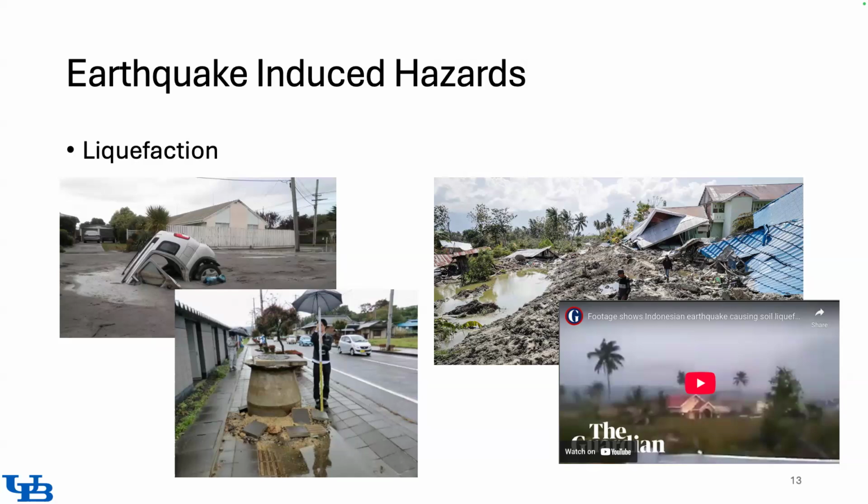And since the pore pressure is increasing, the effective stress is less. That essentially makes one grain float relative to the other and fully lose shear strength. Then it's a state where the sand or cohesionless soil behaves like soup with no shear strength. And if you have a heavy object above a layer that has liquefied, it will sink.